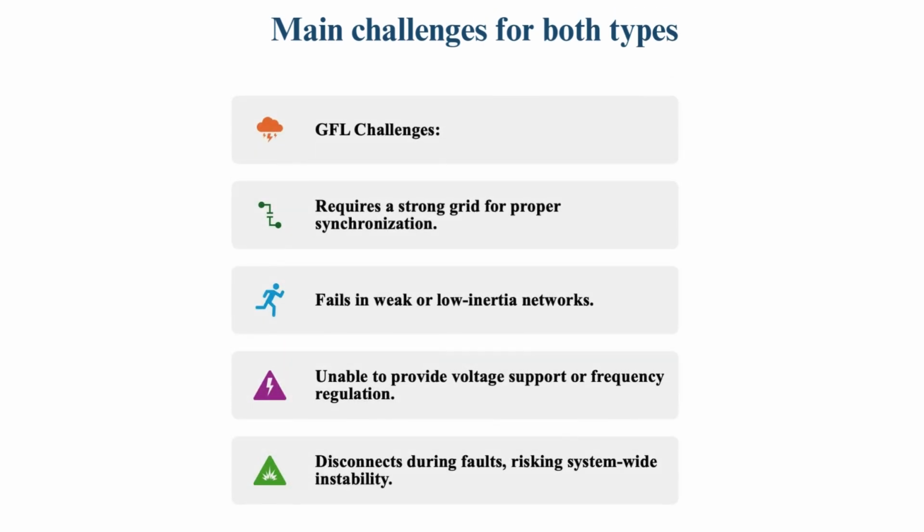GFL challenges. 1. Needs a strong grid to stay synchronized. 2. Fails in weak or low inertia systems. 3. Cannot support voltage or frequency regulation. 4. Disconnects during faults, which may destabilize the grid.